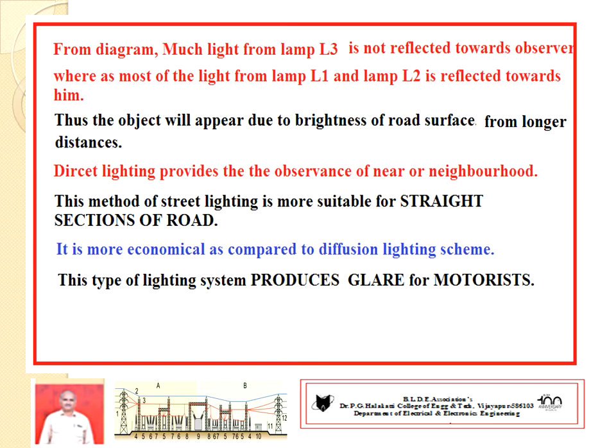So, this method of street lighting is more suitable for straight sections of road where it is available, and it is also more economical as compared to the diffusion lighting system. But this system suffers from the production of glare, and motorists are not free from the glare effect.